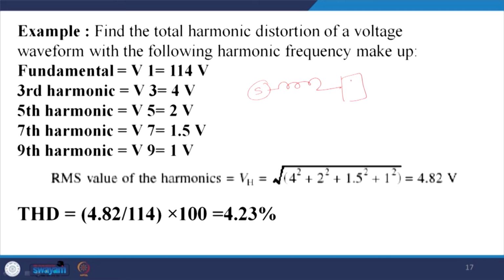And thereafter when you have a diode bridge rectifier, you have a current that is fundamental, thereafter 5th, 7th, 11th, 13th, and if you have a 3-phase 4-wire system, then also the third harmonic. Once the third harmonic current flows through the inductor, it gives this voltage. The 5th harmonic current, once it flows through this inductor, gives this 5th harmonic voltage and so on.